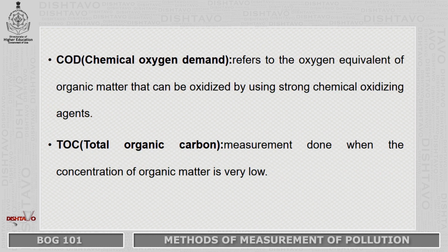We have COD, which is chemical oxygen demand, which refers to the oxygen equivalent of organic matter that can be oxidized by using a strong chemical oxidizing agent. TOC, which is total organic carbon, is a measurement done when the concentration of organic matter is very low.